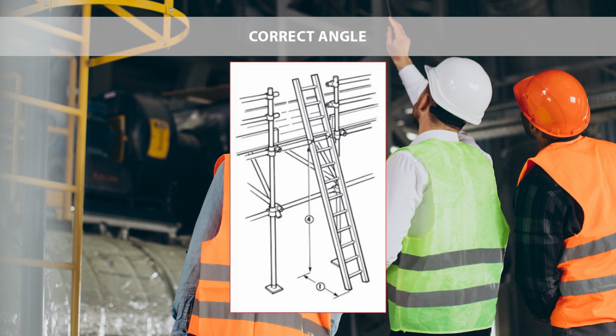That means, for every 4 units of elevation, the ladder must be placed 1 unit of distance from the base. And other precautions: do not load ladders beyond the maximum intended load for which they were built. Secure and barricade ladders when using them in a passageway, doorway or driveway where they can be displaced by workplace activities or traffic.